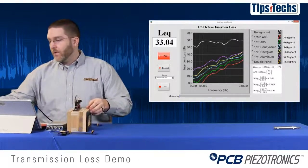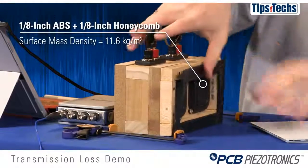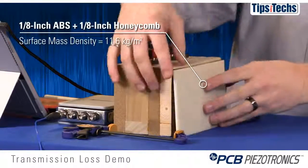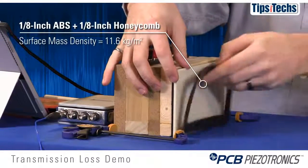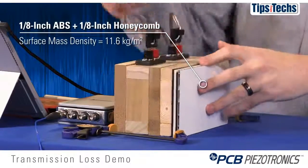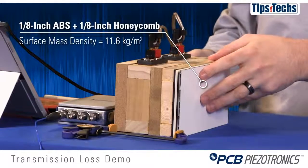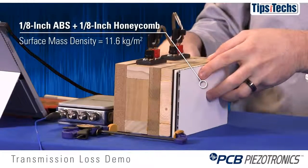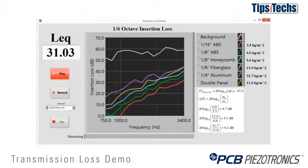Finally, I'm going to demonstrate a double panel system. So now we'll use the 1/8 inch honeycomb and the 1/8 inch ABS with a 1/8 inch air gap between the two of them. So now we have a panel system that weighs about 11.6 kilograms per meter squared surface mass density. It's about the same mass density as the 1/8 inch fiberglass. The single panel mass law would tell us this should have the same insertion loss. Let's see what happens.